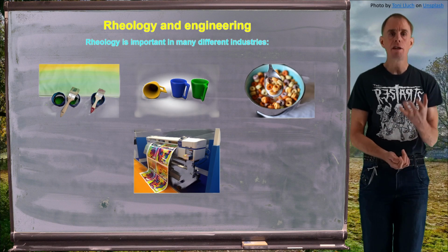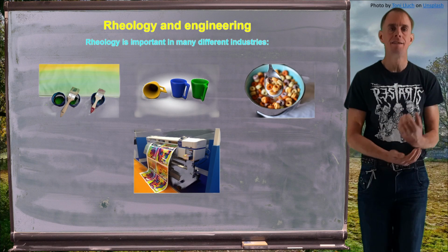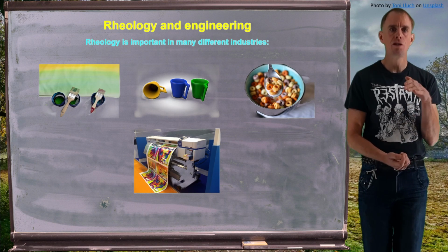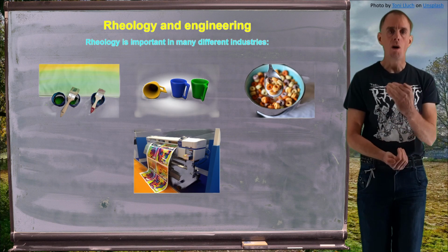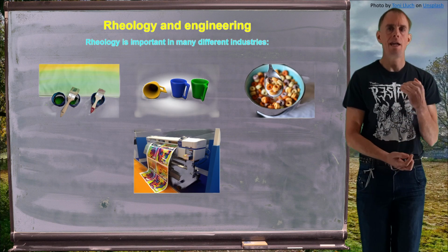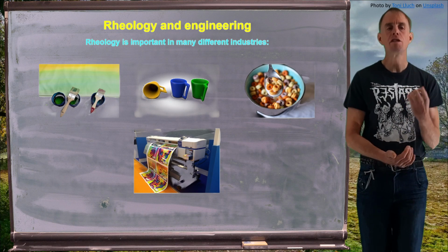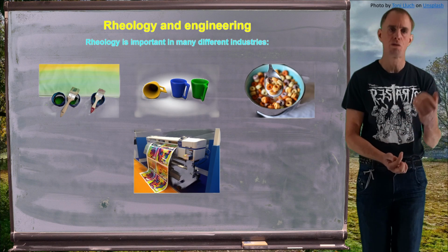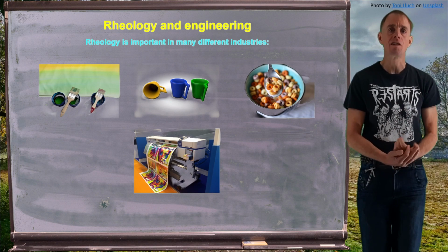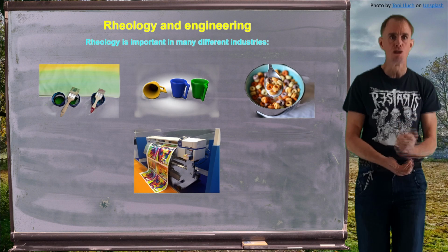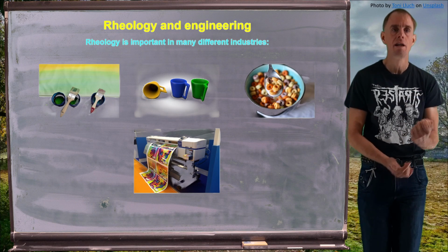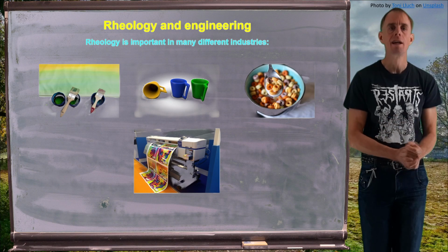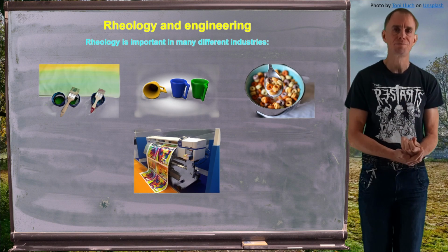But if you think about the science and technology of ink design, how you get an ink to jet from a piezo-based or a thermally based printhead onto a piece of paper in a very predictable, incredibly repeatable, consistent manner, because during the course of one print you're probably ejecting millions of droplets, and each droplet has to behave in exactly the same way, you'll see that actually how you design the ink and how you quality control the ink is going to be incredibly important.